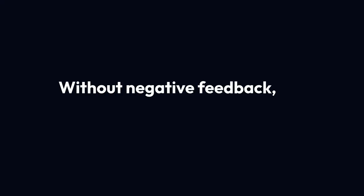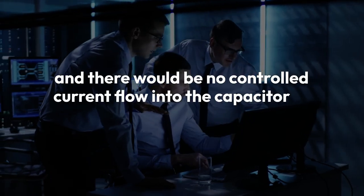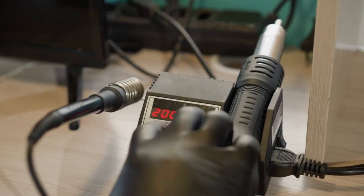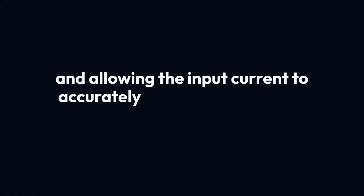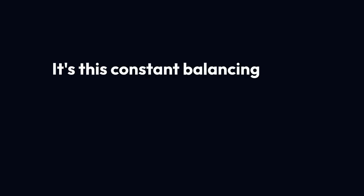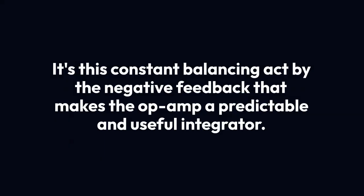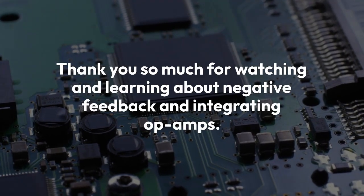Without negative feedback, the op-amp would simply saturate, and there would be no controlled current flow into the capacitor to perform the integration. Negative feedback ensures the op-amp operates in its linear region, precisely controlling the output to maintain the virtual ground and allowing the input current to accurately charge the feedback capacitor, thus enabling stable and accurate integration of the input signal. It's this constant balancing act by the negative feedback that makes the op-amp a predictable and useful integrator.